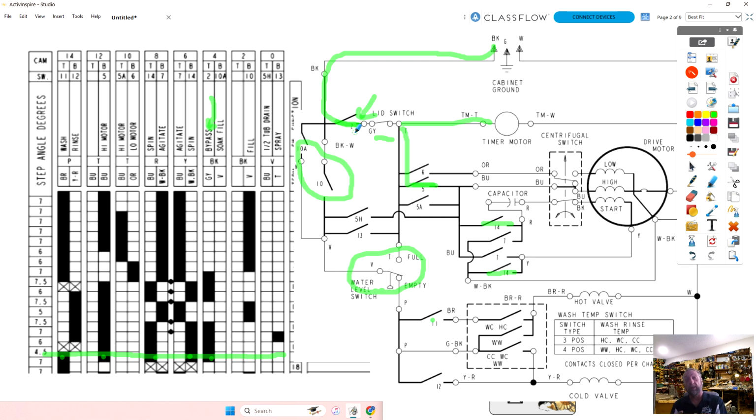They're drum brakes in the direct drive washer, like the back brakes on a car used to be drum brakes. Same principle. When you open that lid and the motor stops, the brake mechanism engages. It's not electrical, it's mechanical. When the motor's spinning, it pushes a lever which releases tension and the basket can spin. When the motor stops, a spring inside engages and locks the brake mechanism.